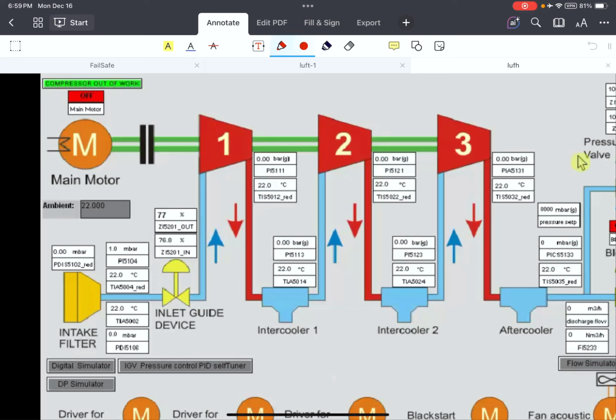So we have these floating point variables stored in some memories inside the PLC, and by using the software available for each manufacturer, or using some interfaces like OPC, there's a possibility to bridge between HMI and PLC. There's a possibility to read those analog values.